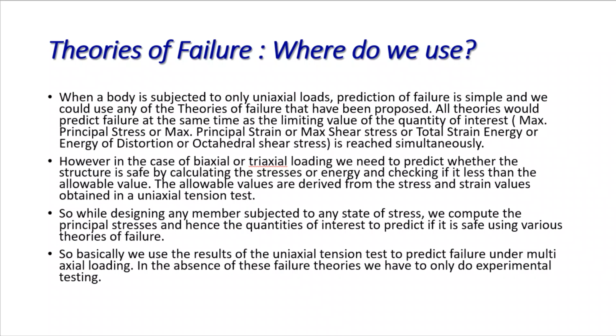So while designing any member subjected to any state of stress, we compute the principal stresses, hence the quantities of interest, to predict if it is safe using various theories of failure. So ultimately what we are using? We use the results of the uniaxial tension test to predict failure under multi-axial loading.